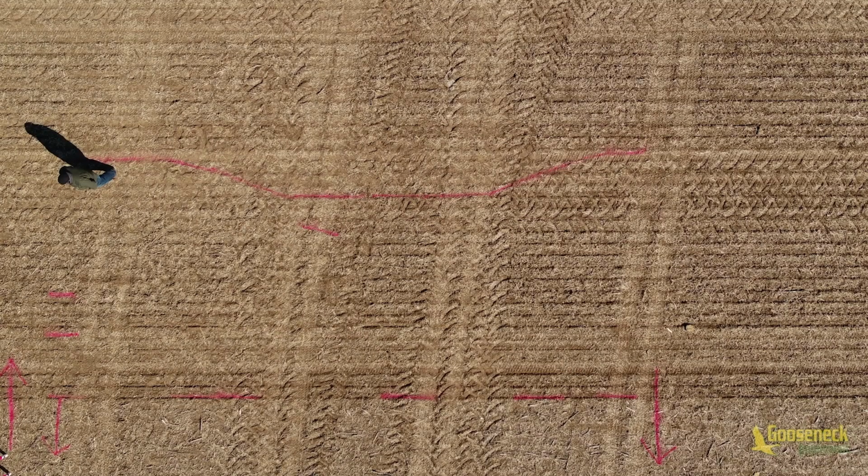After completing the first test run, we need to mark seed placement across the width of the drill for entering the headland and exiting the headland. As you can see, we have marked seed placement with pink ground paint. The markings give us a visual of how the section equalizer times allow a more even distribution across the width of the tool. We call this our chevron or V pattern.